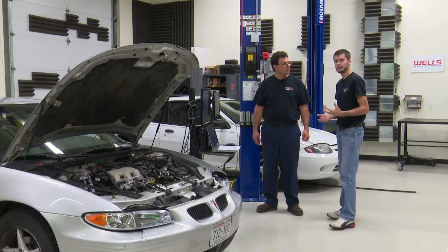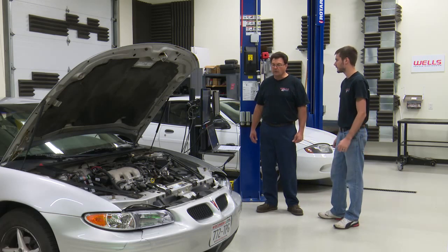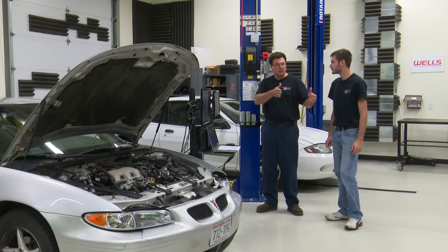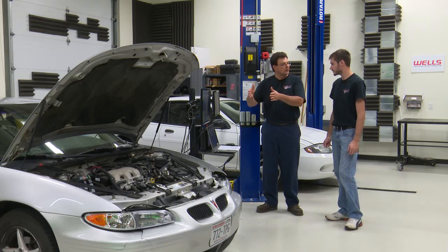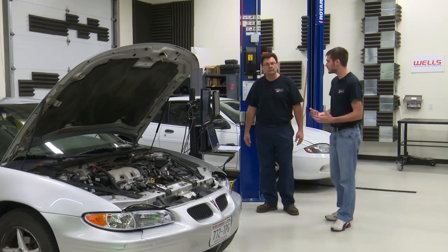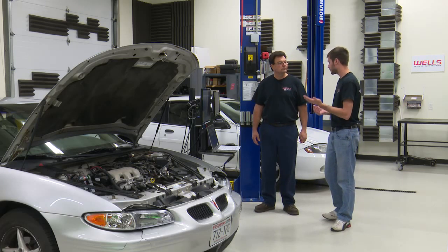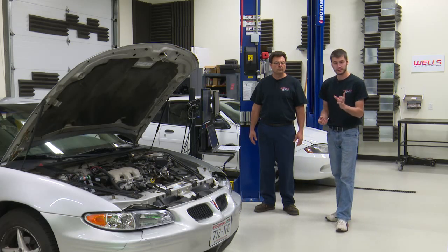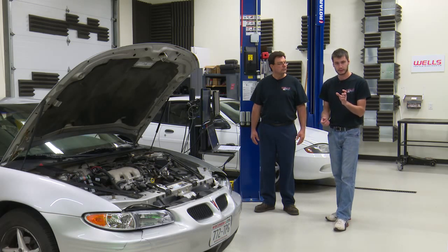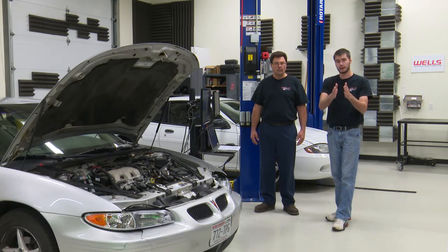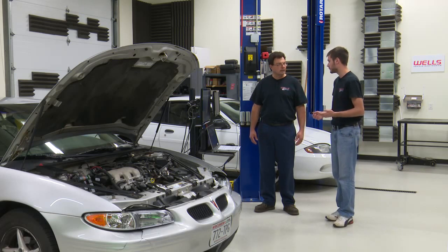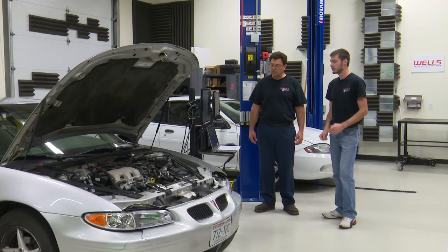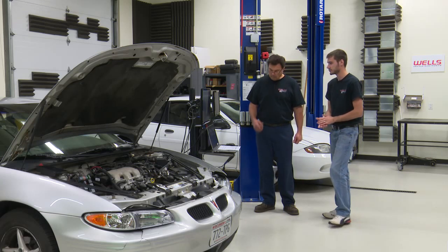So why do we graph with a scan tool, Fritz? Well, we use graphs to watch data in time as the vehicle's running. We can see what the component's doing over time, right? Okay, so it's kind of like the difference between watching the PIDs or the live data, which is like looking at a multimeter where you get the number just for that second, versus watching it on a lab scope where you get that number over a spread amount of time. Exactly. So that's the main difference, and there are some sensors that we really want to watch that on. Definitely. So let's show a couple of those. Let's show some graphing. All right, let's do it.